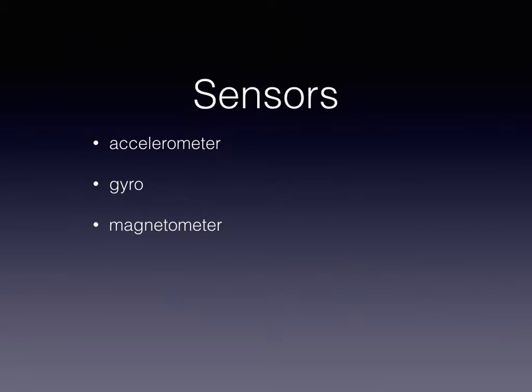Everyone has an accelerometer. That's how rotation of applications is detected. Not all of them have gyros and magnetometers. There's a fourth item, which is referred to as device motion, which uses an algorithm to do error correction on data, sort of integrating data from all three sensors.